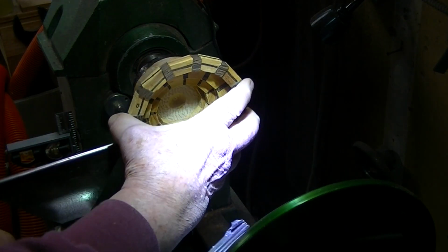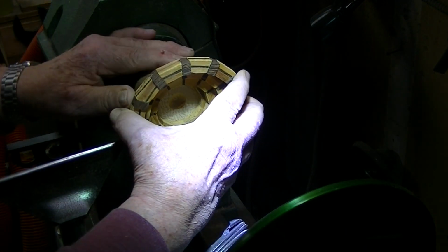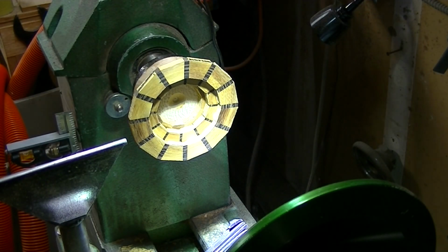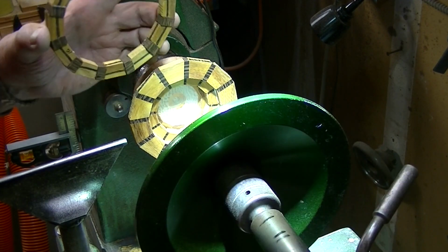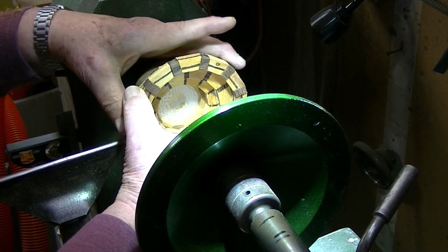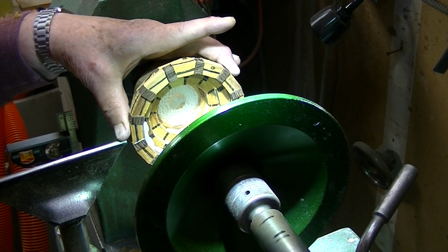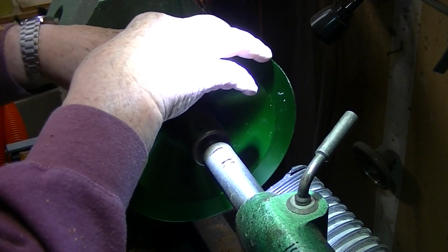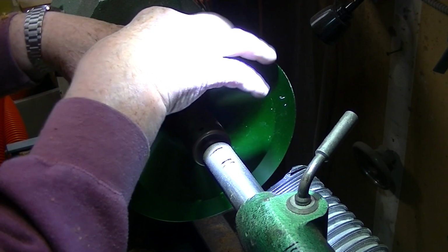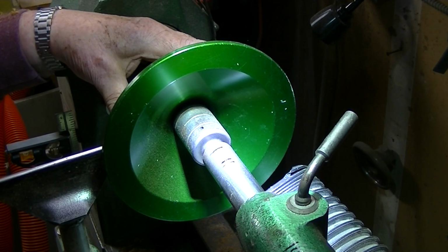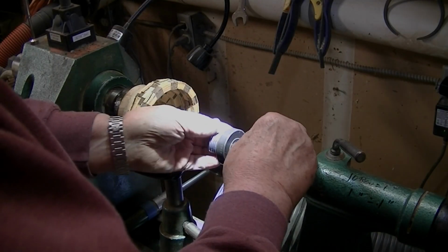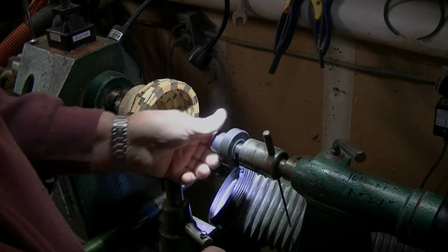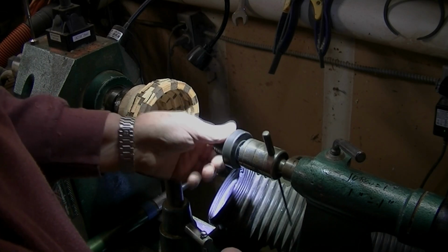We build hollow vessels in 2 stages, top half, bottom half. This way we can look at hollowing them out much easier. Each will look like a bowl when we're in the process of hollowing it. So here goes the ring. As you notice, the spacers now are the wenge, and the tulip wood is the segment. On the bottom, it was the other way around. You go to a point in the center when they're roughly the same shape and size, and we then changed from segments on one to segments cut on the other.